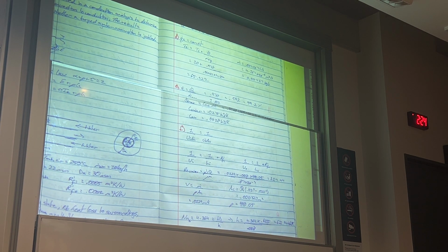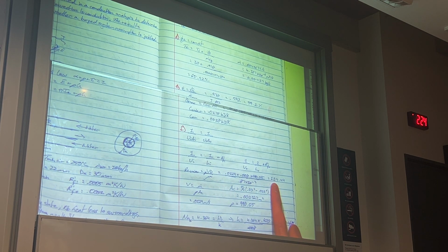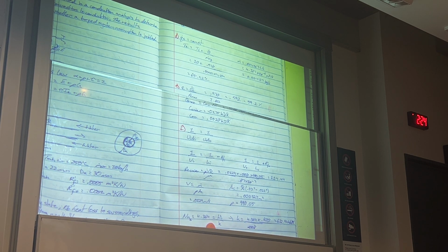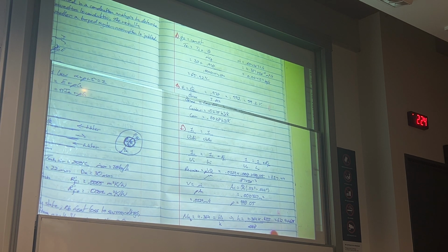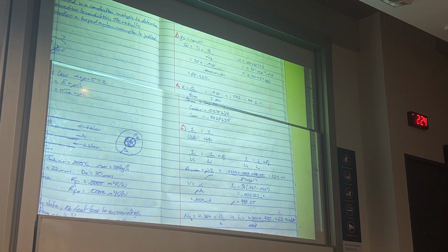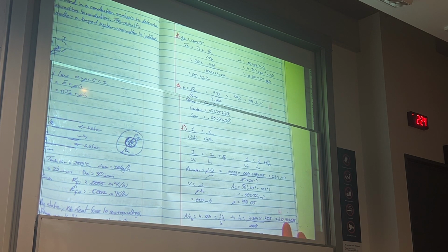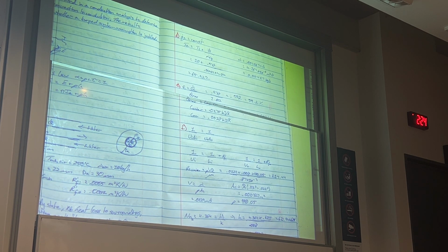So now we just want to go ahead and characterise our flow. I've gone ahead and calculated my Reynolds number, so I've got a standard laminar flow. So I can use this Nusselt relation. I can calculate h, and this is for my outer surface. I end up with my outer surface heat transfer coefficient being 586.41 watts per meter squared Kelvin.